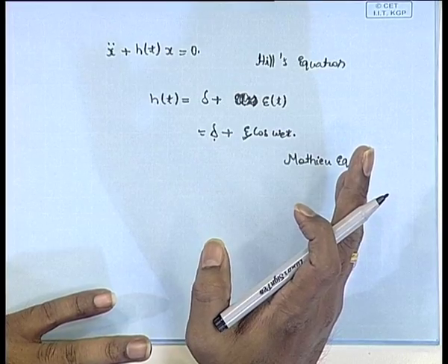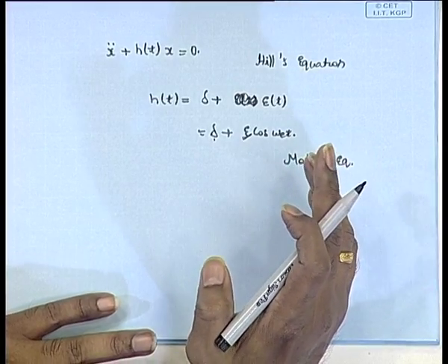Now, GM is a property of the ship, and it is a property that can be modified as a result of probably a wave. So, if you have a wave, it can modify GM. There are other external properties also that can modify GM. But in general GM is a property of the ship, and that natural GM, not subjected to the wave, is what we call GM 0. It is the natural component of the GM, and that is given as delta here.